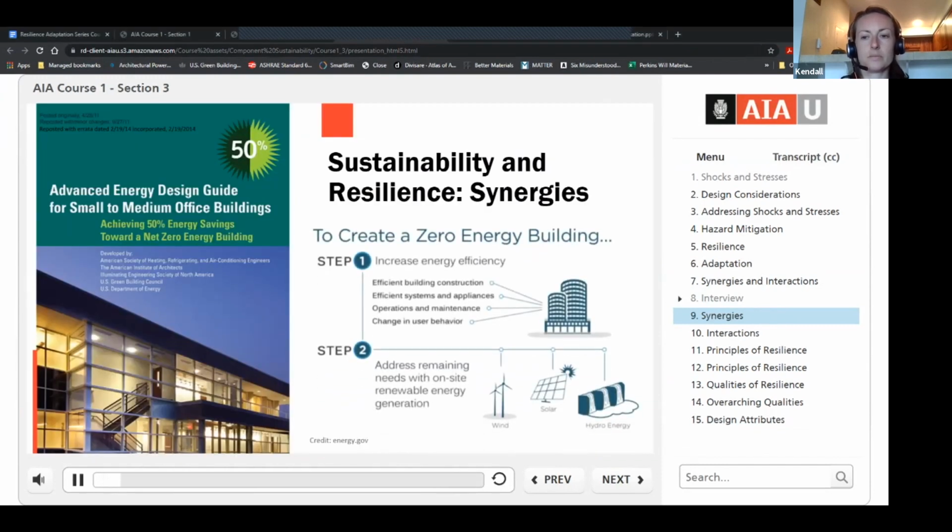There are synergies between sustainability and resilience. Passive strategies such as increased insulation for energy efficiency, for example, is an area where sustainable design and resilient design align well. Increased insulation contributes to a facility that can maintain comfort and passive survivability in the aftermath of a disaster that knocks out power. In addition, a more efficient building will extend the fuel efficiency of any backup power system that a facility may have. And if that backup power is provided by a well-anchored PV system, the link between sustainability and resilient design is even stronger.